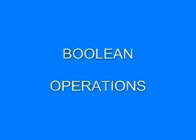Boolean operations. You can use the Boolean operations to create complex solid models. The following tutorials are excerpts from my tutorials online at youtube.com. These tutorials show how to use the operations of union, subtract, and intersect. The union command defines a new solid that consists of the common and uncommon volume between 2 or more solids. When using the subtract command, 2 sets of solids are selected, and a single solid will be created based on the subtraction of one solid from the other. The intersect command defines a new solid based on the common volume between selected solids, and all other material is discarded.